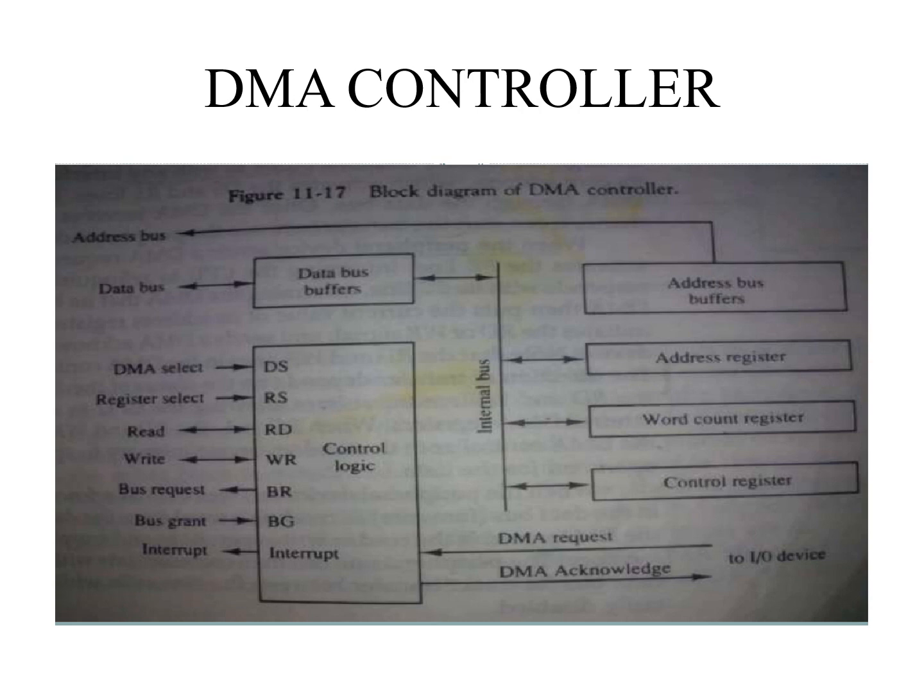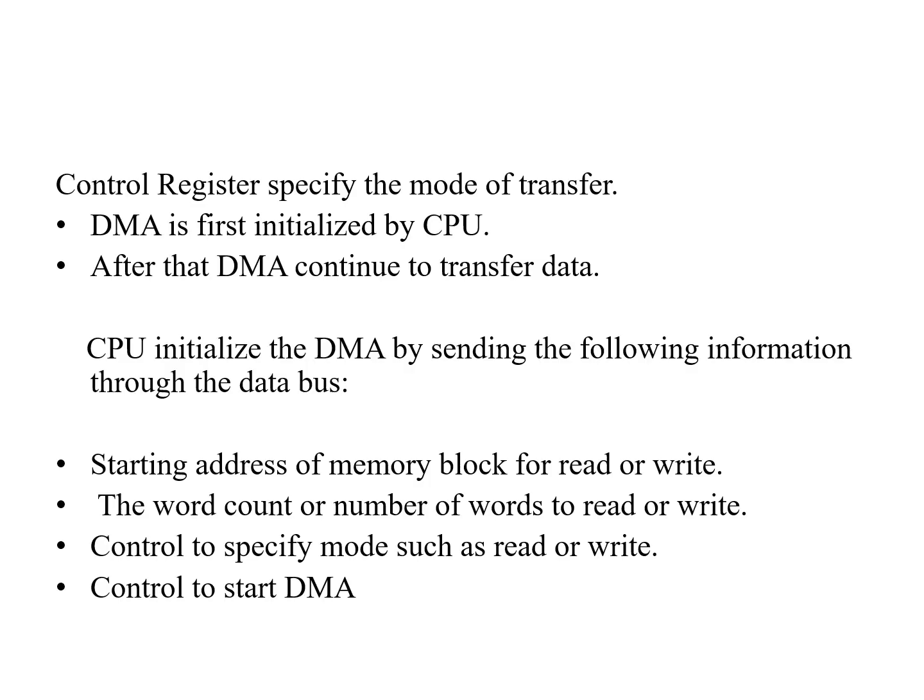Address bus buffer, it deals with the internal address. Address register, it shows the address of the data to be fetched or written. Word count register, it tells the number of words to be transferred. Control register, it specifies the mode of the transfer.